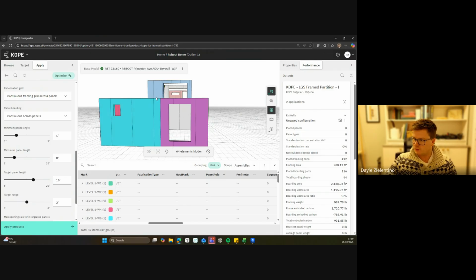It will come to 15 foot and realize that it's landed in the middle of the window opening. Now, you can't normally do a panel with a window opening like that. So then it looks at what's my minimum and what's my maximum length. It draws back, works out how to handle the window framing, and keeps drawing back to a point where you can position the panel break before it starts a new panel that can handle this window condition.